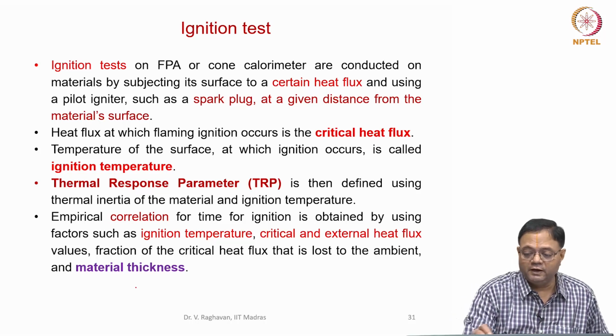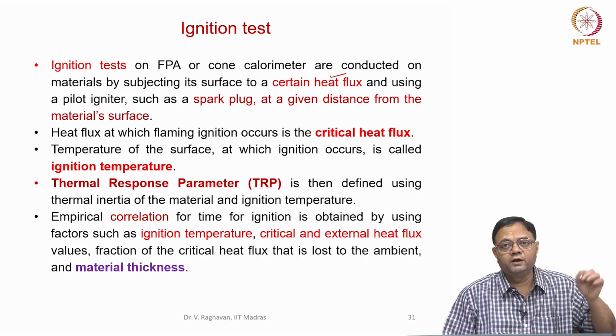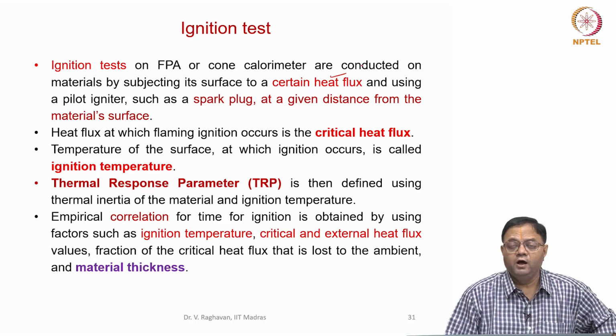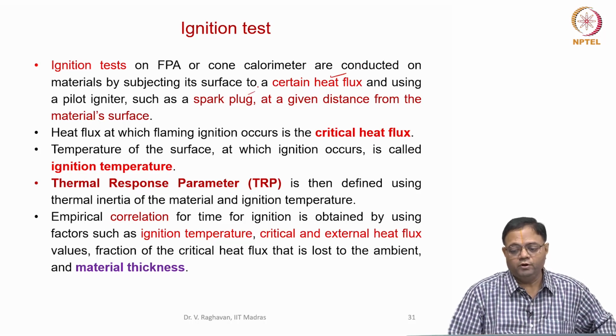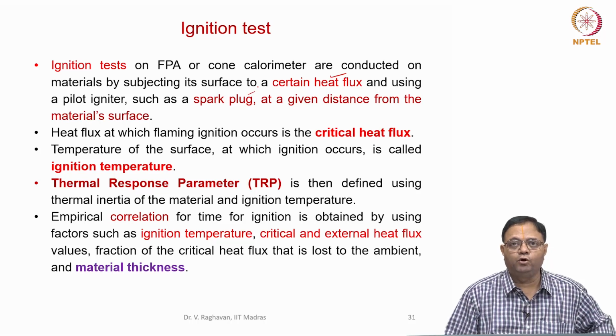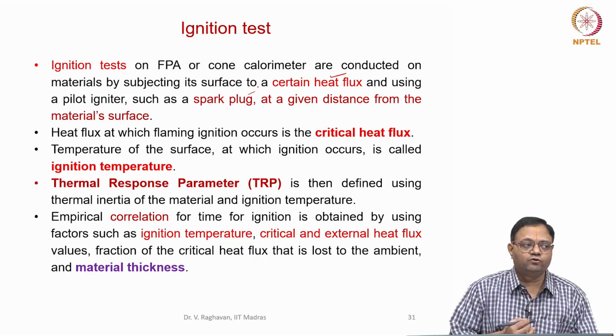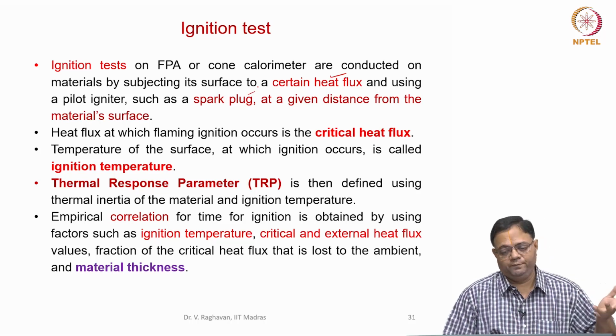There is a critical heat flux at which you will see that the ignition source can produce ignition, through a spark plug or any external source kept at a given distance, again based upon standards. As I told you, you cannot keep the ignition source very near to the surface of the material or very far away.